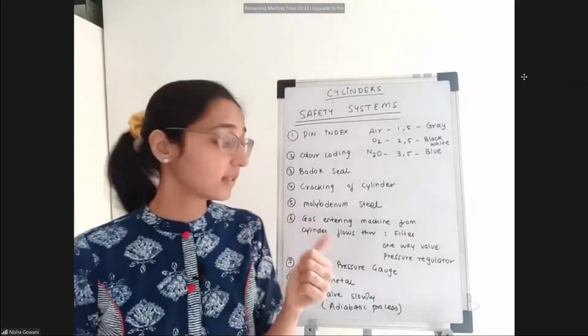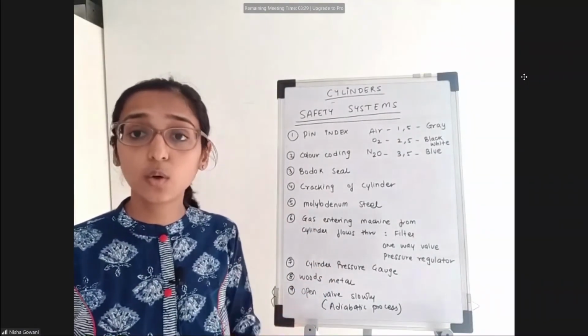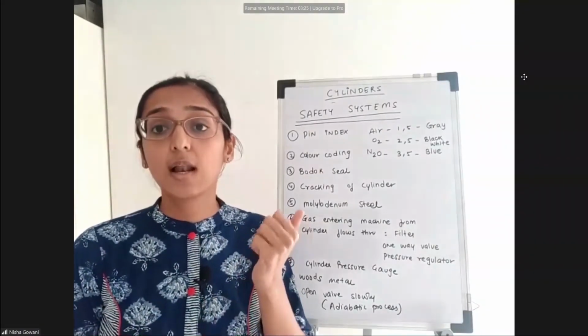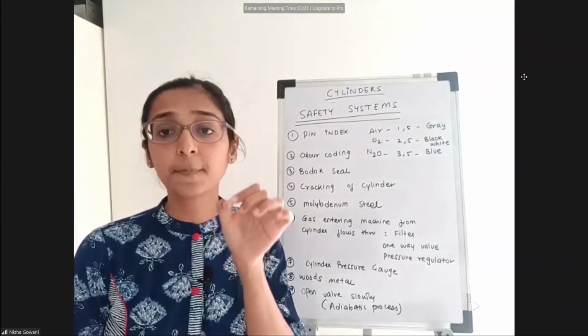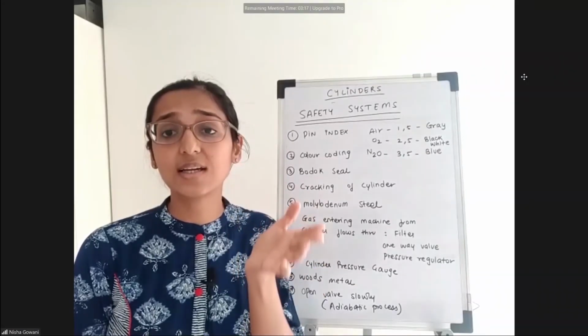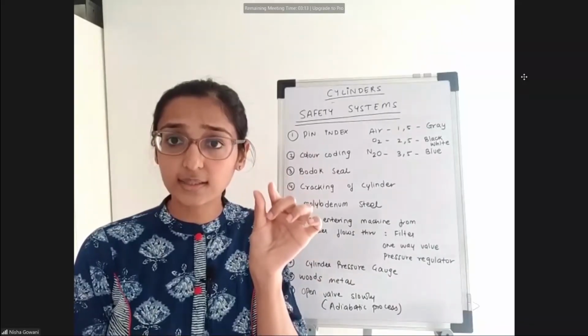Now, why are we doing this cracking of the cylinder? This is related to opening the valve of the cylinder very, very slowly. Don't open it very fast. If you open the valve very fast, a large amount of gas goes through this narrow port, and that will cause a rise in temperature. There will be generation of heat in that small little space.